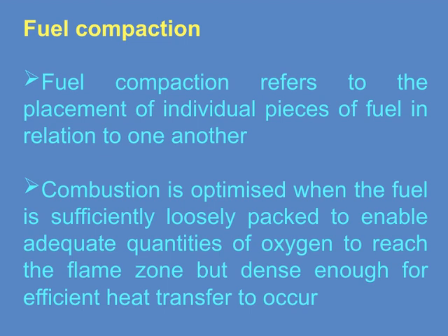If the fuel is too loosely packed, oxygen can easily reach the flame zone, which is great for maintaining good combustion. But if it's packed too tightly, it can restrict airflow and reduce combustion efficiency. On the other hand, if it's too dense, heat transfer becomes less efficient, which can hinder the overall burning process.